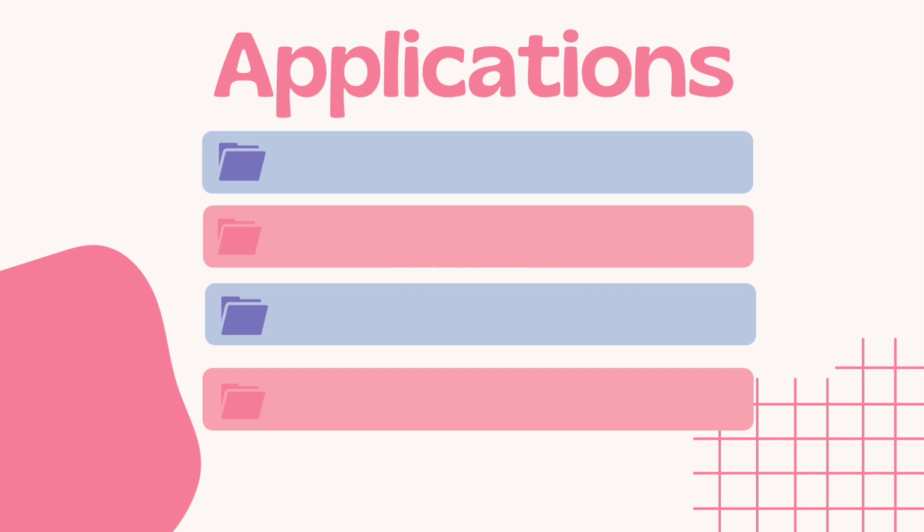For the applications, the PIN diode is used as a high voltage rectifier. The intrinsic layer in the diode offers a partition between both the layers, permitting higher reverse voltages to be tolerated. The PIN diode is used as an ideal radio frequency switch. The intrinsic layer among the P and N layers increases the space between them. This also reduces the capacitance between the regions, thus raising the level of isolation when the PIN diode is reverse